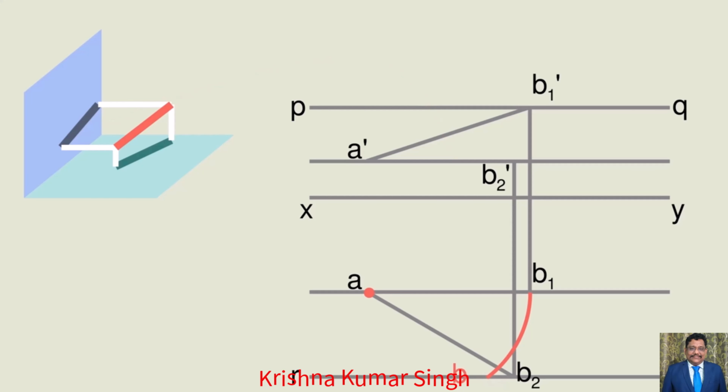Step 3. By taking the compass, by fixing a length of AB1, draw a locus arc from point B1 until it touches the locus line of B and name it as point B. Join point A and point B. This is nothing but the original and final projection made on HP.